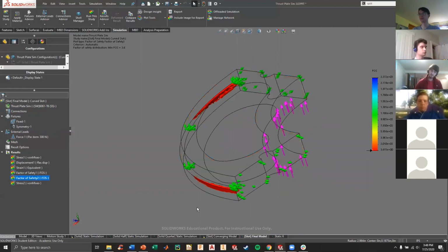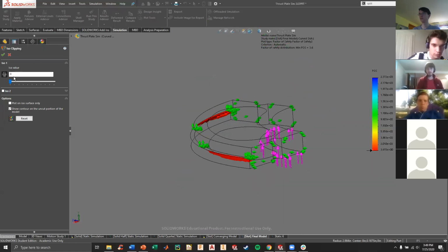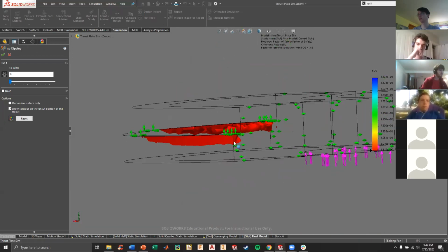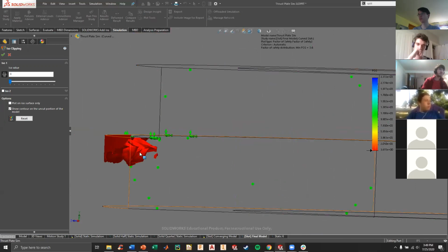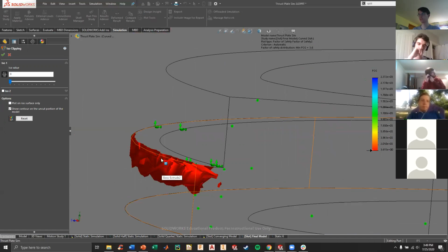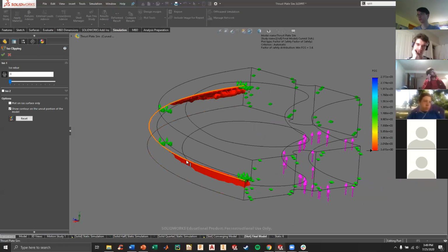But something you can look at here is doing something called iso clipping. It's the same factor of safety plot, but I've turned on isoclipping, which essentially you can either remove anything below or above whatever value of interest you're going to specify. So here I have it only showing areas that have a factor of safety below 8. This is probably about the point where I might say that this has stopped being a singularity and is actually just a stress concentration. So singularities happen at a point, and they do affect the areas outside of it. But this is getting into a pretty large area of high stress that probably wouldn't necessarily only be caused by